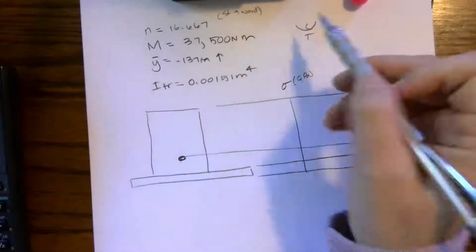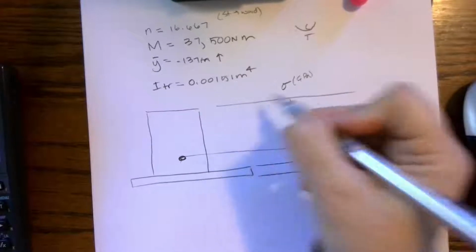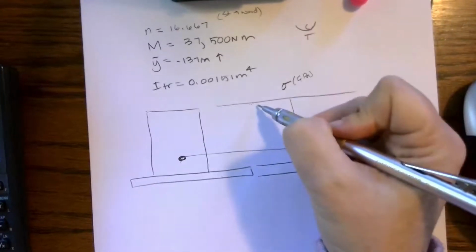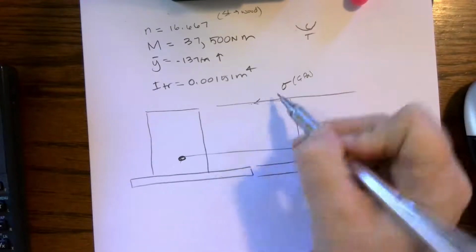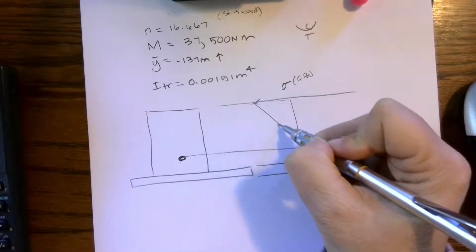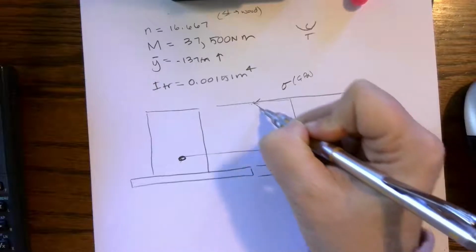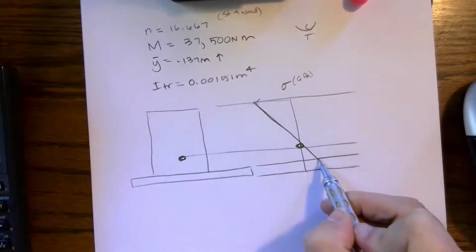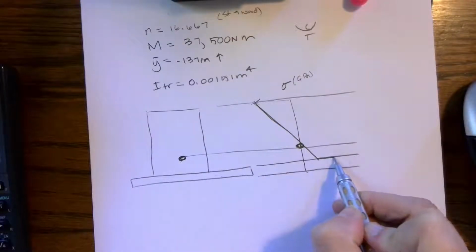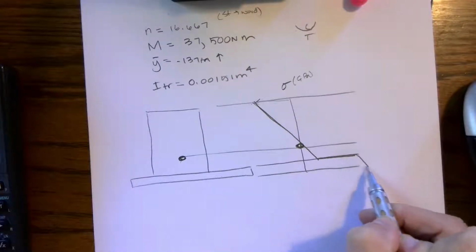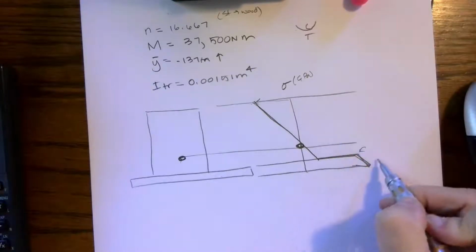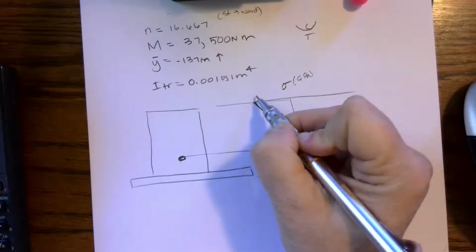I know that we have compression on the top, and I like to just go ahead and draw my compression to the left, like it's negative, because I'm going to show that we're getting shorter. Okay, and we're going to come through here, pretend that that hit right there on 0, and then I know that we're going to have a jump where we change materials. Okay, so I know what this is going to look like before we get started, but we're actually going to find all of our numbers to fill this in.